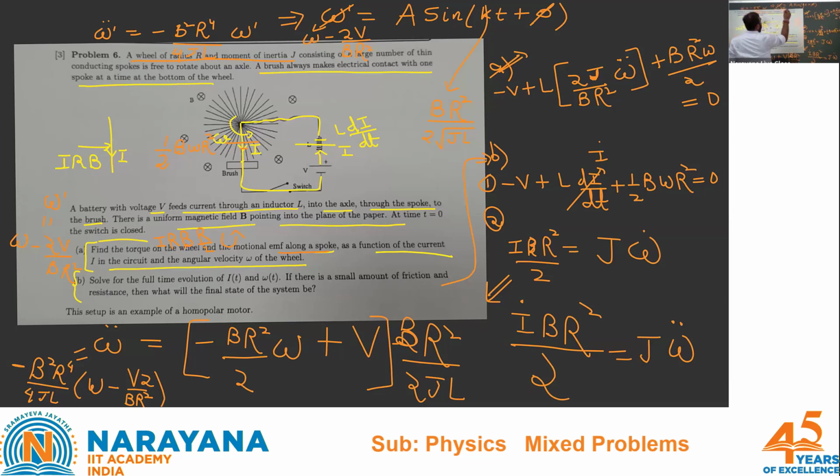Now, I think the only unknown in this equation, which is required, omega t is your answer. There are two unknowns, A term and phi term, and you know two values. At t is equal to 0, now use boundary conditions. At t is equal to 0, you should make omega 0, and you should also use the current to be equal to 0, because inductor is there, so current cannot change suddenly.